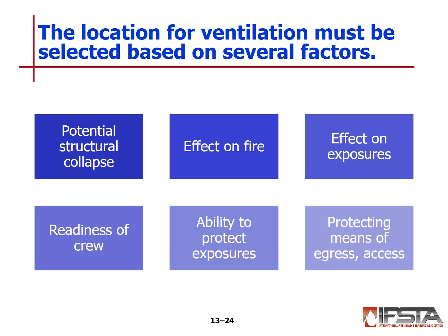Potential for structural collapse, we talked about that through building structure and fire behavior. Looking at the indicators of the building and seeing things we need to be aware of, and knowing what type of building it is, whether it's a 1, a 2, a 3, up to a 5, and what effect that fire is going to have on that building construction. The effect it's going to have on exposures. We talk about garages. How many times do you hear a garage fire that has now impinged on the house, and now you're dealing with a house fire as well?